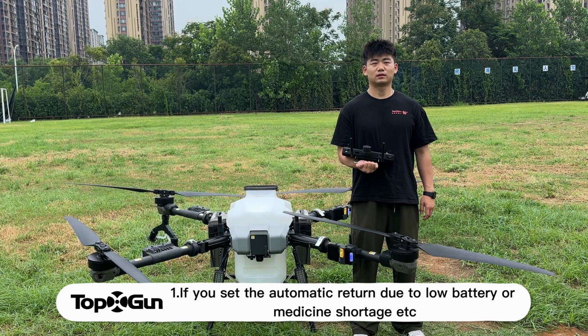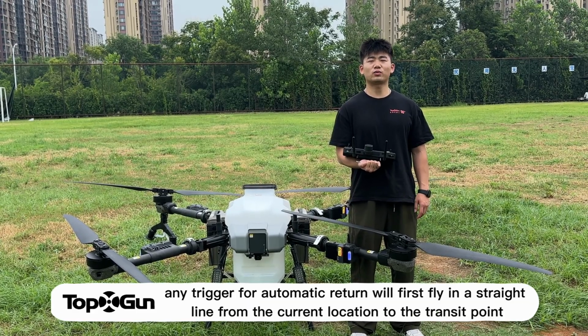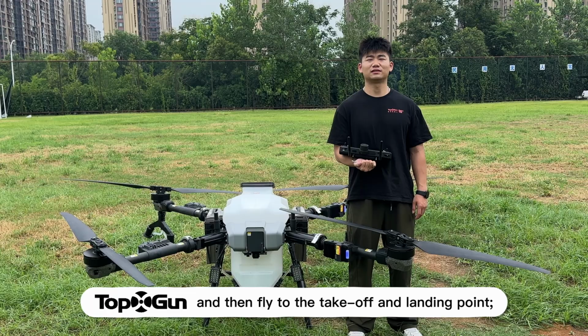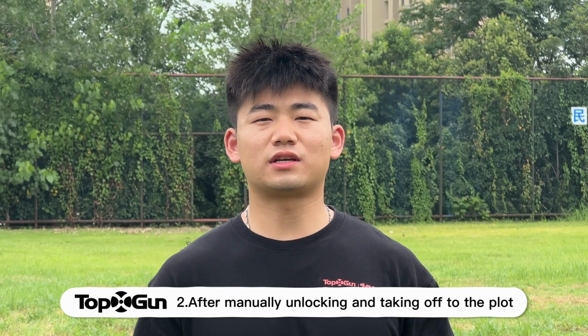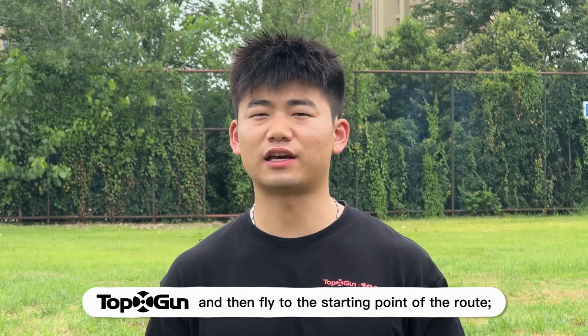Precautions. 1. If you set the automatic return due to low battery or medicine shortage, etc., any trigger for automatic return will first fly in a straight line from the current location to the transit point, and then fly to the takeoff and landing point. 2. After manually unlocking and taking off to the plot, when entering automatic operation, it will first fly straight from the current position to the transit point, and then fly to the starting point of the route.